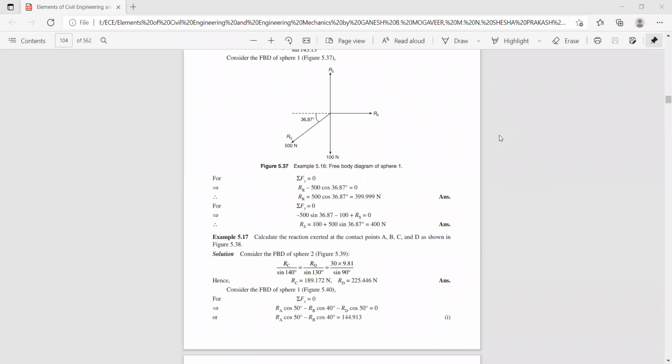In first quadrant, both the components are positive, correct? Yes, sir. Second quadrant, it may be one is positive and one is negative. If you resolve the resultant, you can take minus sign, no problem. Some of the problems you may have these type of things. Otherwise, directly in a concurrent force system, you have to calculate the sum of the horizontal components, the sum of the vertical components. Then use the equation, R is equal to square root of sigma f of x square plus sigma f of y square. Then find out the angle theta, tan inverse sigma f of y by sigma f of x.